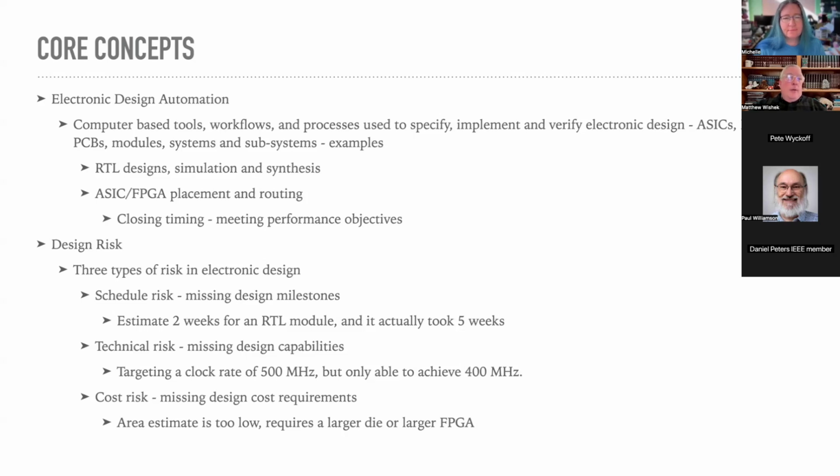So in terms of EDA, some of the core areas where we use EDA tools are RTL designs and simulating RTL designs, synthesizing them, and then as we move those RTLs into implementation in ASICs and FPGAs, we have placement and routing. One of the key things in the implementation phase is closing timing, meeting the performance objectives, right? We're targeting particular clock rates. Are we meeting those? And if we're not, that's a pain point, if you will.